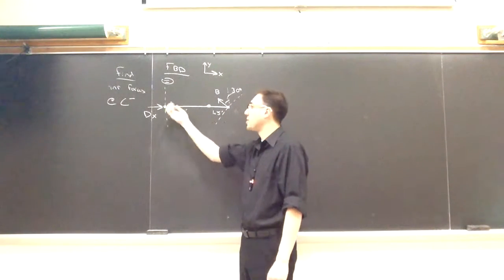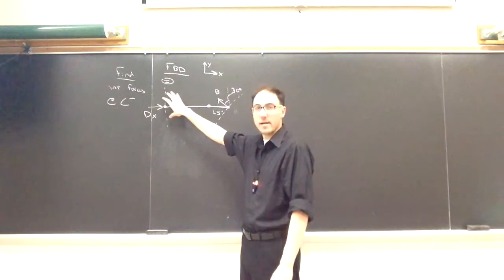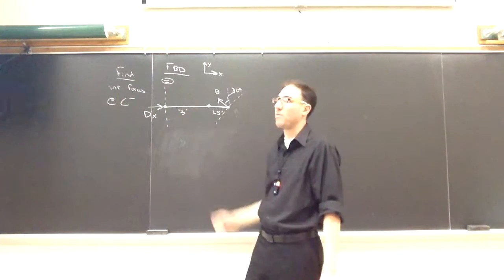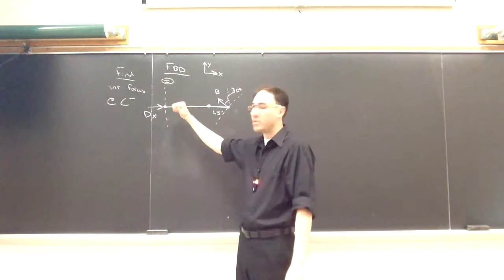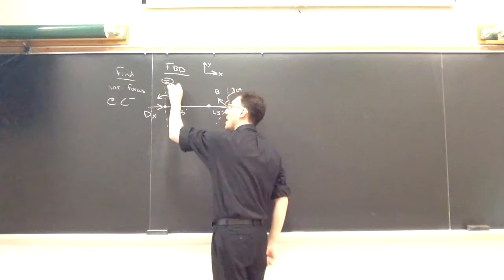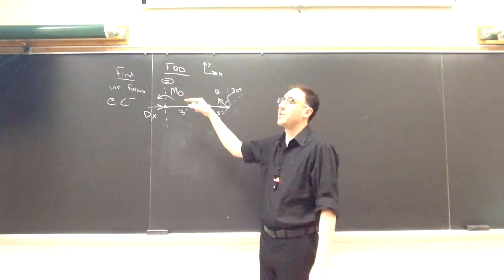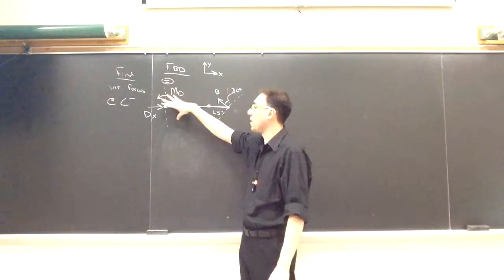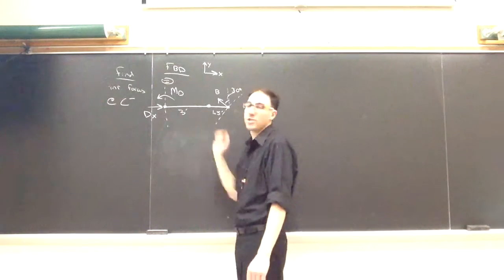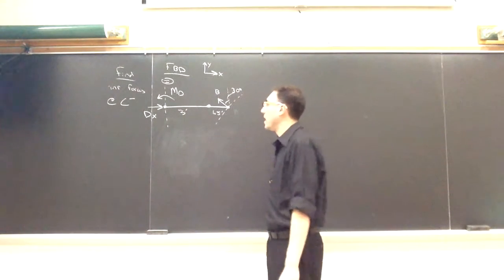And then moment-wise, if we try to rotate around the z-axis at that collar at D, we can't do it because it's going to bang into the top and bottom of the collar on that pipe. So any rotation around the z-axis is prevented. Now around the y-axis it is allowed, but in 2D we're only concerned about rotations around z. So there'll be some couple there, I'll call M sub D, and I'll assume it's in the counterclockwise direction. This is what the pipe is doing to the collar. So the collar can't rotate this way, nor can it rotate that way. We're not at the internal yet. Externally, I'm making this assumption. It could turn out to be the other direction, and this would prevent rotation clockwise or counterclockwise. We have three unknowns from that.